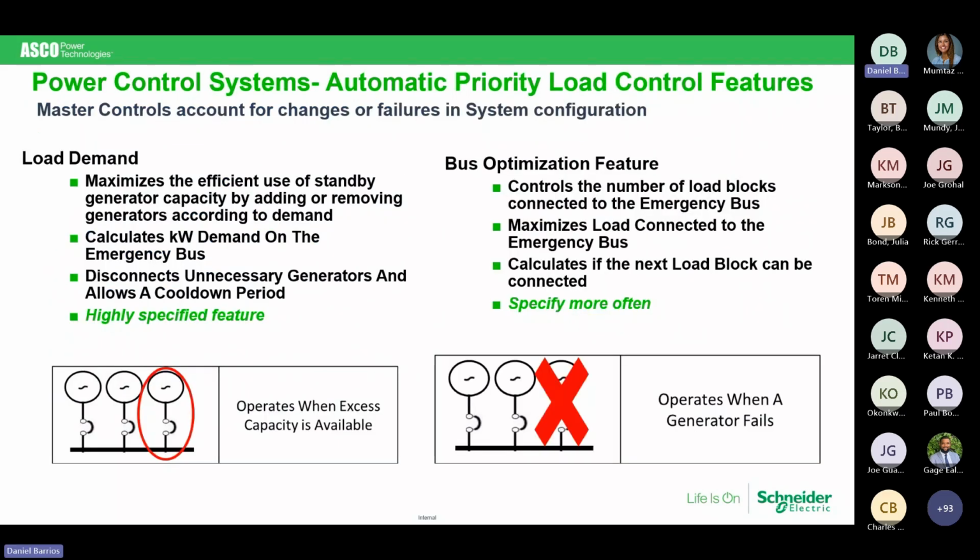All right, so we look at load demand, these two terms, and I'm sure Mumtaz would like to speak to you in depth about this as your projects come up. This maximizes the efficiency used by the standby generators. It disconnects the unnecessary generators. This is highly specified in many areas now, for two reasons. Number one, diesel fuel or even natural gas fuel is expensive. Secondly, you may be in an area where you're concerned with the amount of emissions or such.